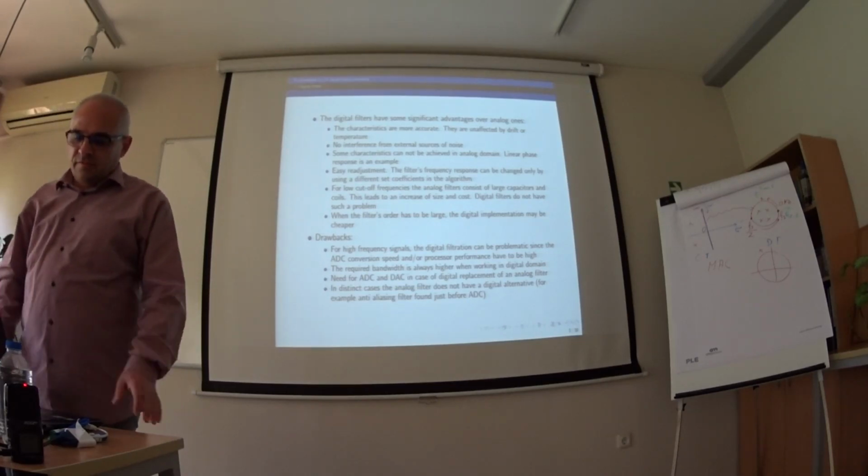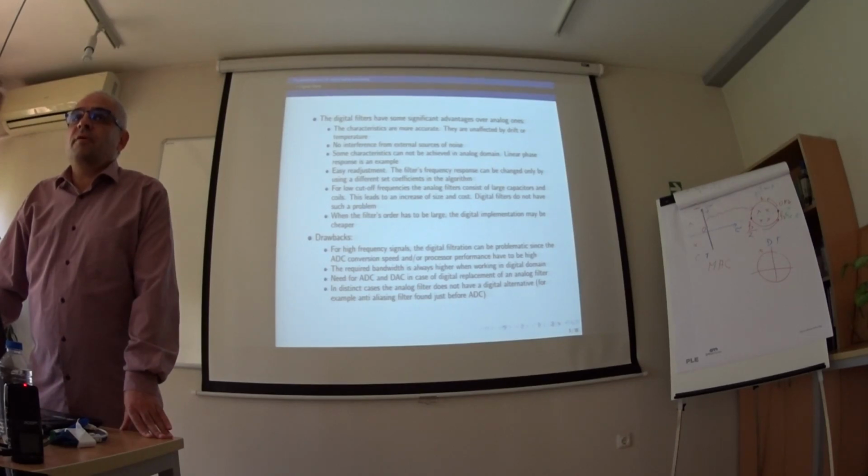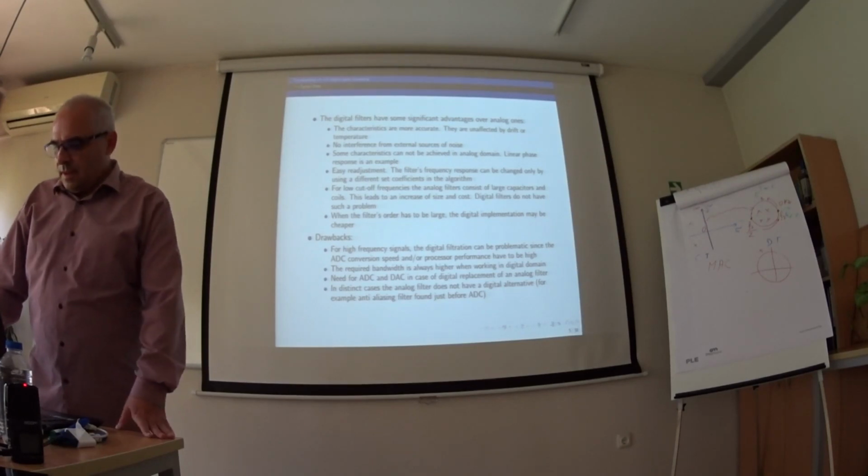And what is the advantage of using digital filters instead of analog? There are many. Accurate processing. We don't have coils, capacitors, resistors with their temperature and time drift. Everything is mathematical operations which are exact, and we have very stable processing.